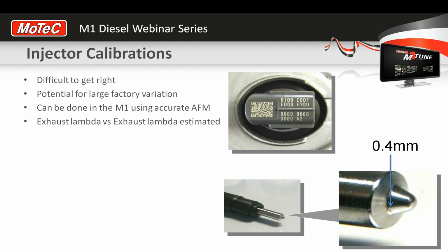And the holes are so small that certainly some of the, let's say cheaper manufacturers, not necessarily Bosch, and this is only my reading of it, struggle to get every single hole on every single injector exactly the same. So what you get is each individual injector doesn't flow precisely the same amount of fuel for any given pulse width.